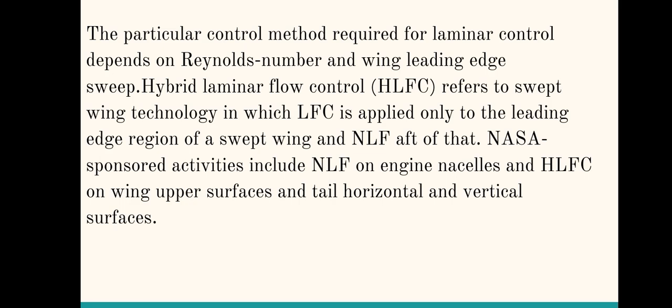Hybrid laminar flow control, HLFC, refers to swept wing technology in which LFC is applied only to the leading edge region of a swept wing and NLF after that. NASA sponsored activities include NLF on engine nacelles and HLFC on wing upper surfaces and tail horizontal and vertical surfaces.